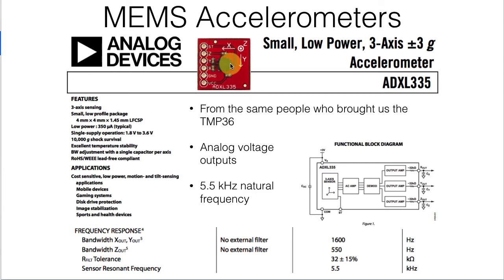The advantage of a system like this is that it's very simple, with very little programming involved. We can connect these outputs directly to analog inputs on our microcontroller or to any other system that needs some sense of what the gravity is. This device, it's important to know when you go and work with it in the lab, takes a 3-volt input maximum. So the supply side should be anywhere between 1.8 volts and 3.6 volts. Make sure you don't connect that to 5 volts or you'll tend to damage the chip.